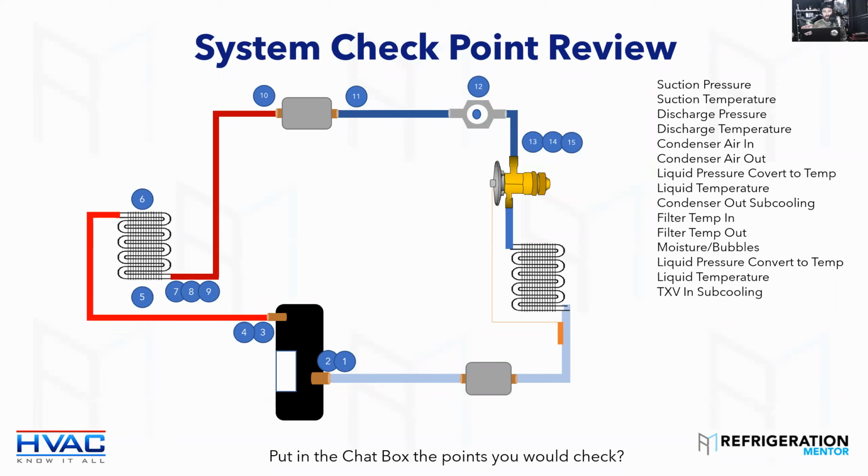And a lot of people say you don't need a sight glass, but I find sight glasses are very, very useful, especially if you know what that sight glass is supposed to be doing at certain times, because the sight glass isn't always clear, even during normal operation. There's times where a hot gas bypass valve could be open, and when it's feeding hot gas from the discharge into the evaporator, sometimes your sight glass starts to flash, but that's normal. So you really got to understand what you're seeing and what you're looking at.